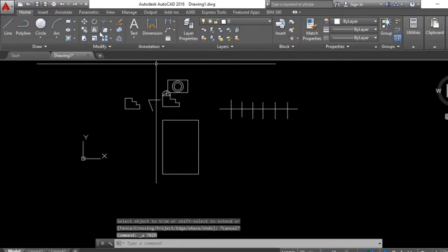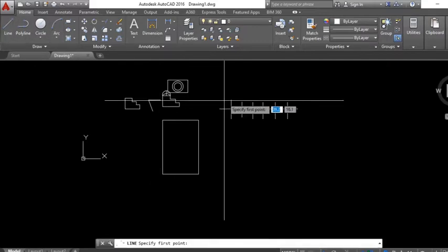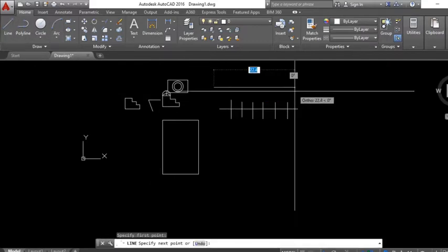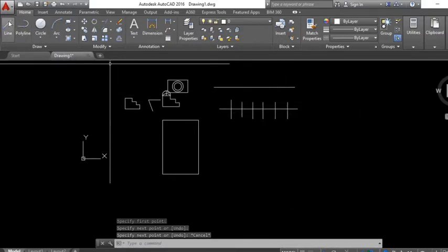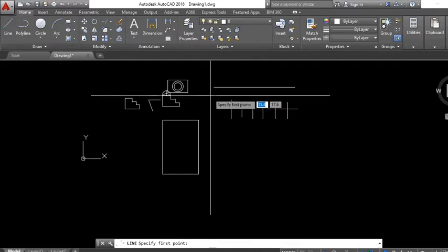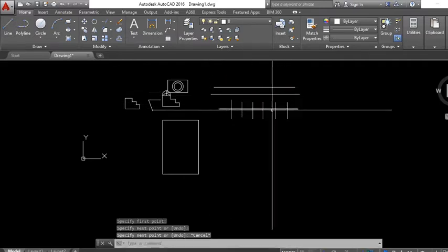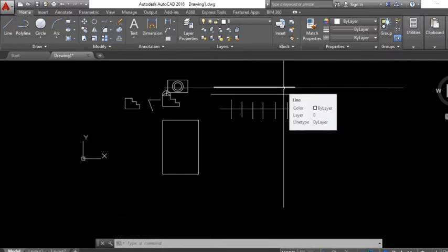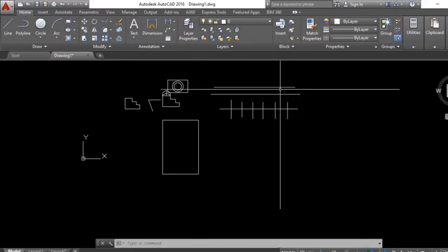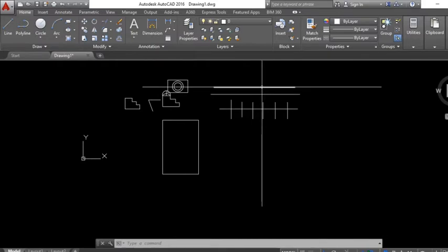Right. So if you click this down, we're going to have extend. So that's the extend command. The extend command means I have to extend some lines to some point. So let's say I'm having this line on top, and there's another line here. Let's say this one. Alright, two lines. But I want to extend this line to that end. So I want to extend this line to that top line over here.